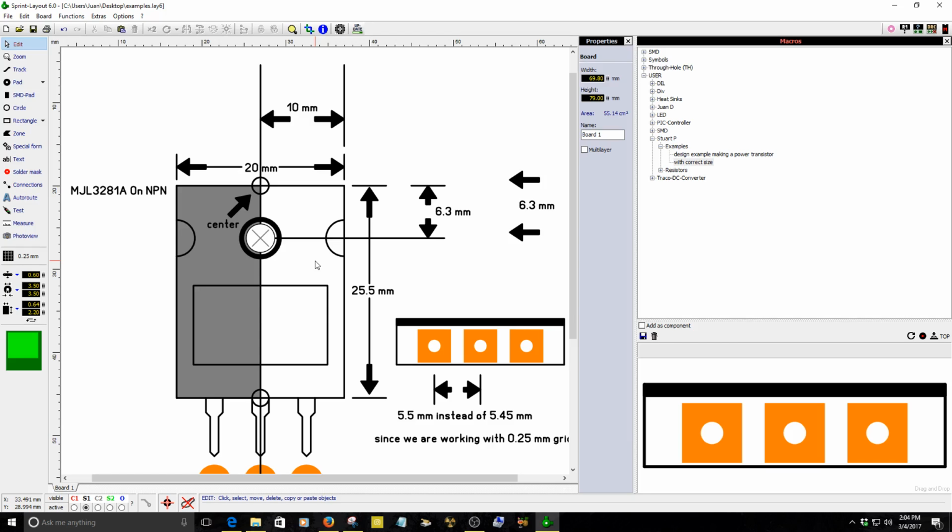Also one important thing: after you print out the PDF, try to compare it with the actual PCB and place it on top of the printing of the guide to see if they are matching, because sometimes the software that we use for printing the PDF, virtual printing, is not accurate, and it needs to be accurate.